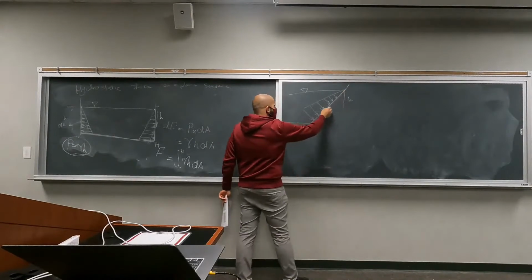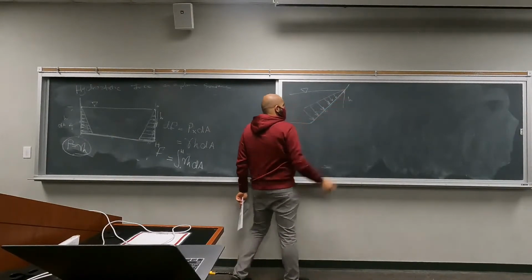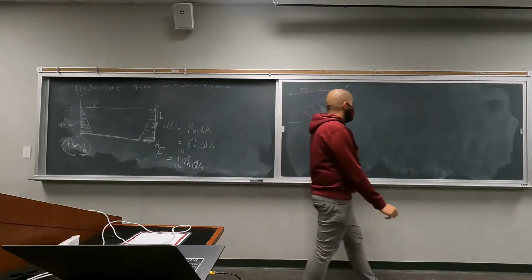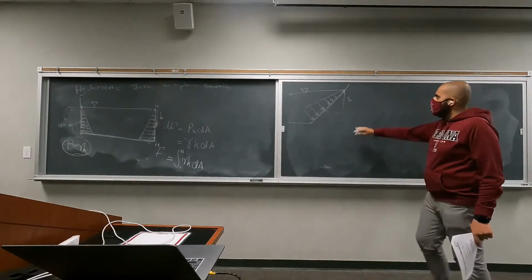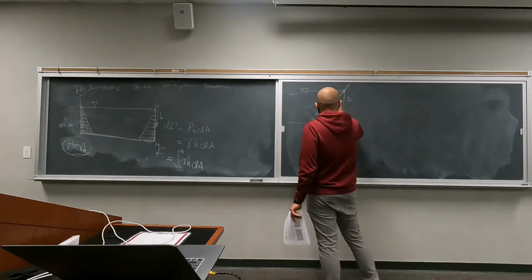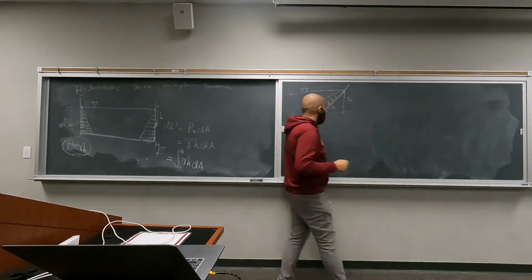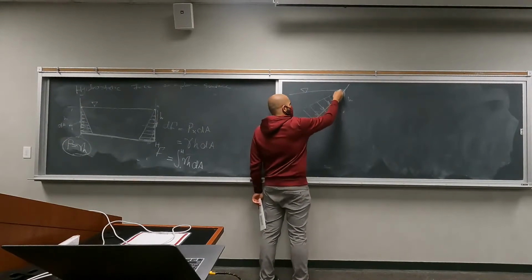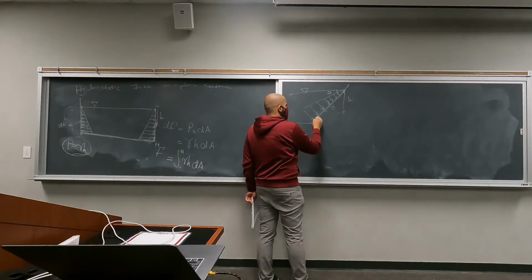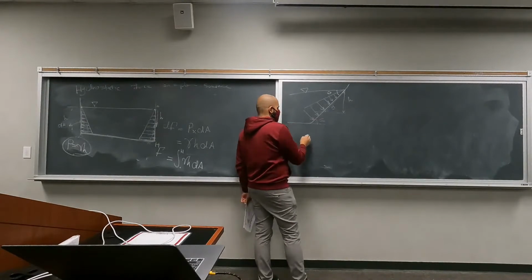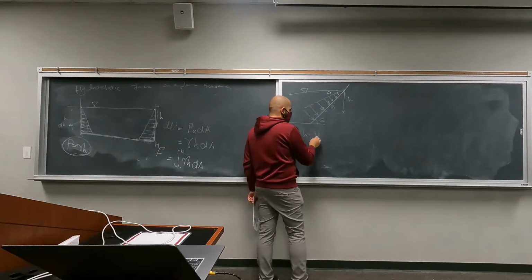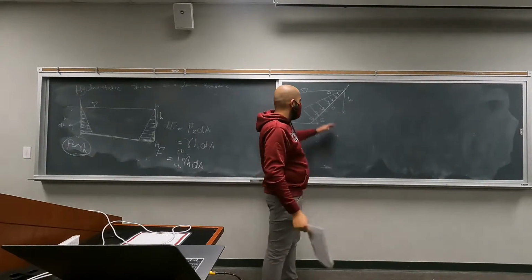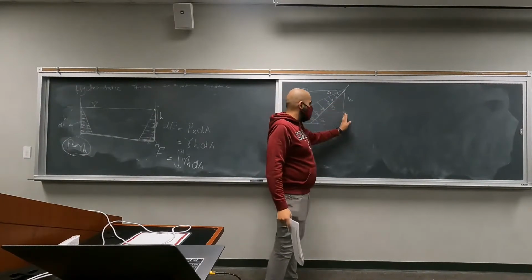We learned that from the inclined manometer. So this length is not the important factor. This height is, height h. Let's call the length y. And what is the relationship between y and h if you have the angle theta here? This h is equal to y sine theta, essentially the projection of this length on this axis.